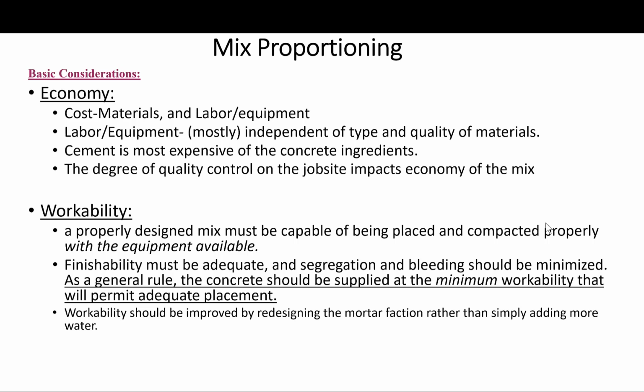It should be noted here that in addition to cost, there are other benefits to using a low cement content. As we discussed before and will discuss later, shrinkage will in general be reduced when we reduce the cement content, and there will be less heat of hydration, if you remember when we discussed the hydration of the cement.